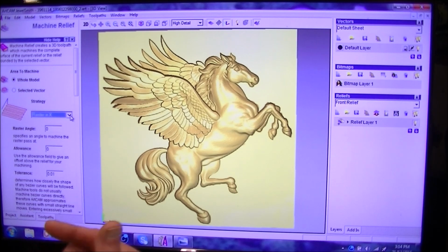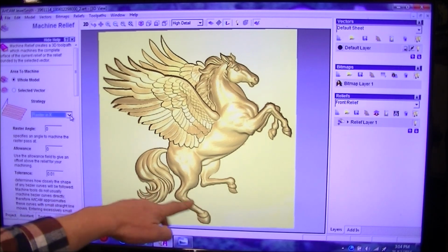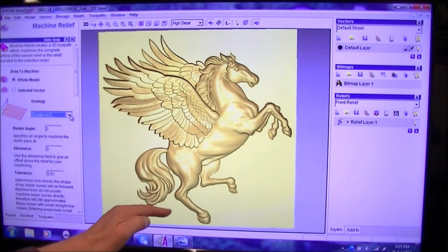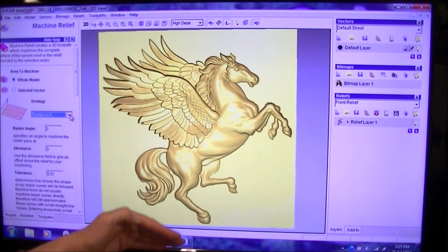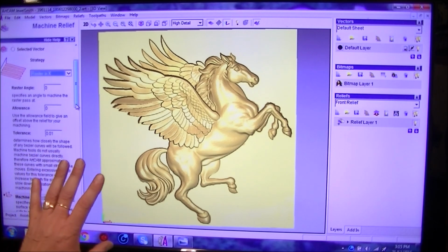I'm going to go in 5mm at a time, and we'll set that up in the dialog in a minute. It's going to run back and forth in the X plane and go all the way through, then drop down another 5mm and take material out, and another 5mm and take material out. We don't need to bother about any of this. Leave it as standard.